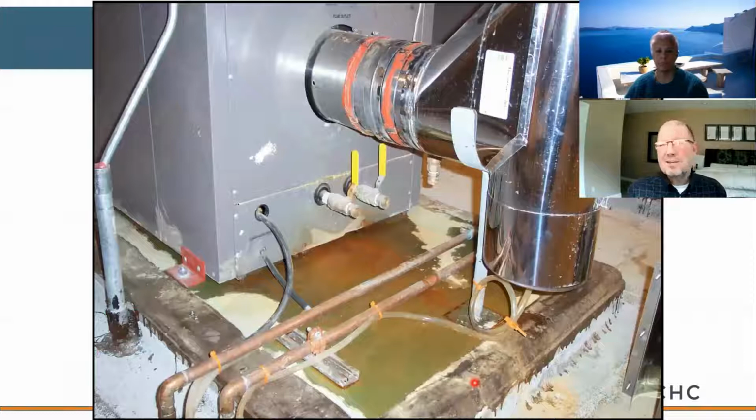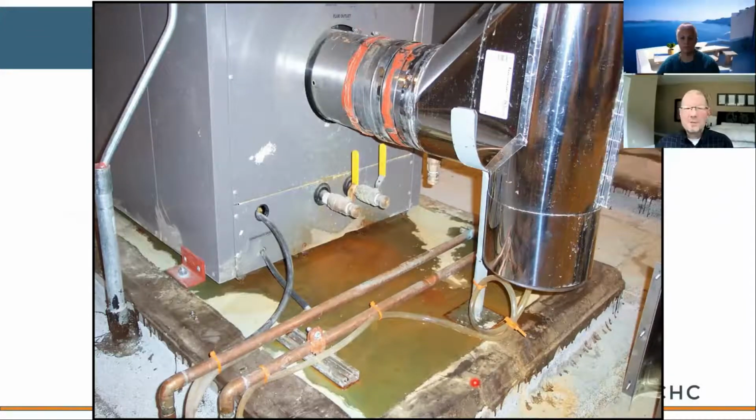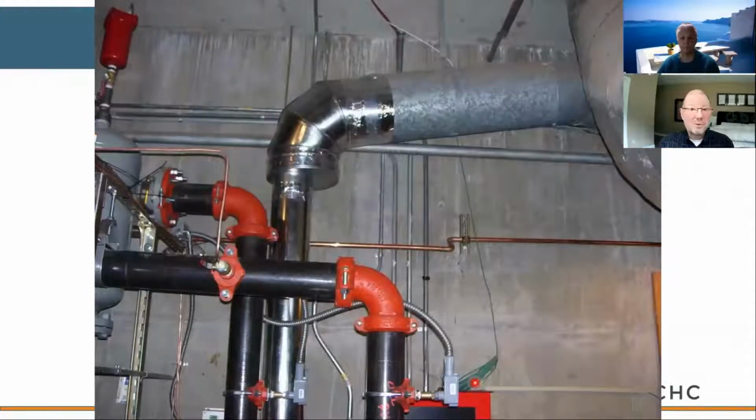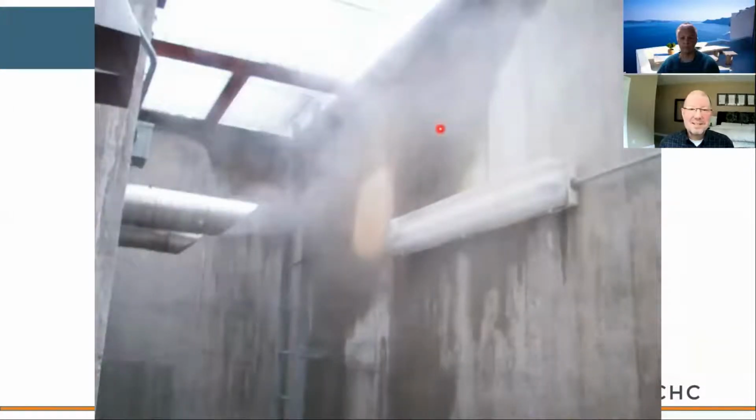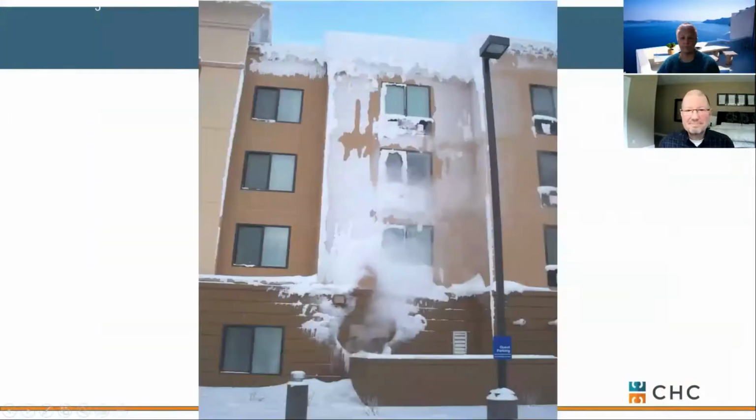A preamble here. We see a lot of issues in the field, specifically around boilers, but it could be around pumps and chillers, whatever you want to call out. A lot of it are venting issues, venting challenges. We'll spend more time on that when we get into boiler fundamentals. Guys doing retrofit, taking a condensing boiler into an existing galvanized flue. You can't really do that. You can try, but it's not successful. We see architects sticking us into basements, and we're having to deal with sidewall venting. That creates some challenges. Also, flue gas recirc that gets drawn in through our outside air.